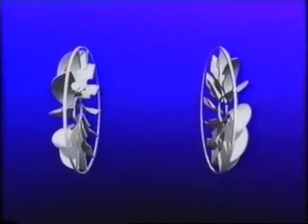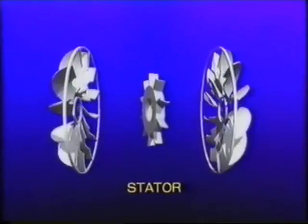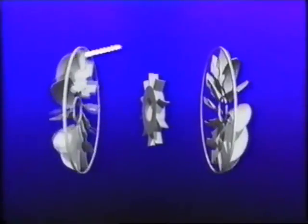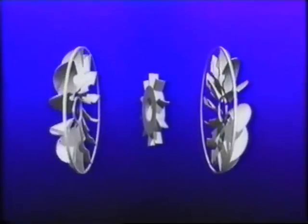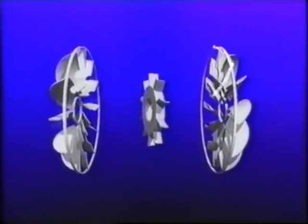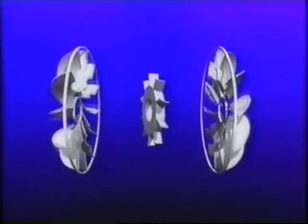Don't worry, we can solve this problem by placing a stator between the pump impeller and the turbine runner. As you can see here, the stator changes the direction of the returning fluid so that it matches the direction of the pump impeller. Now the pump impeller is being rotated by two forces moving in the same direction, one from the engine and the other from the fluid. This causes the torque converter to amplify the torque from the engine.